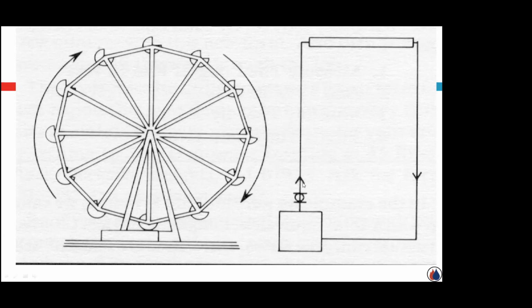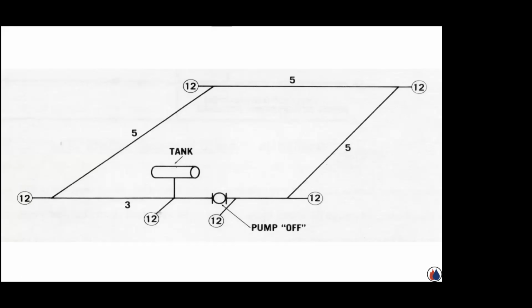Same thing here. Whatever energy it takes to go up that riser, I'm gaining it on the riser coming back down. What I do have to overcome, and that's the job of the pump and the motor, is the frictional resistance to get this thing spinning. So pump head has nothing to do with height, it has everything to do with frictional resistance.